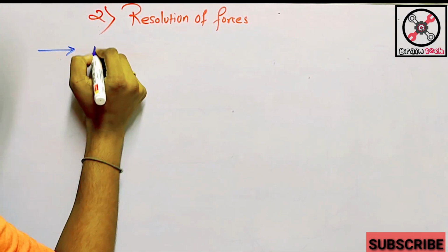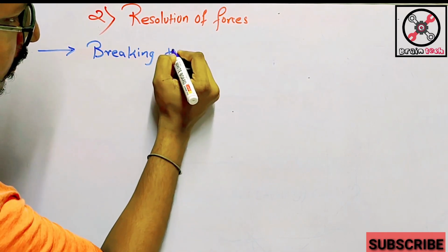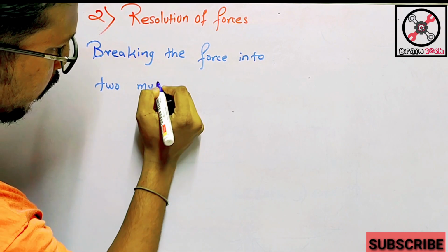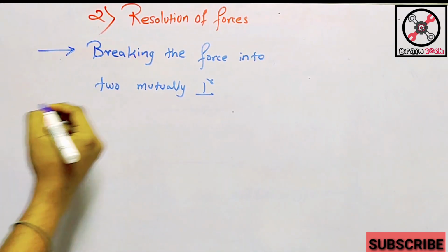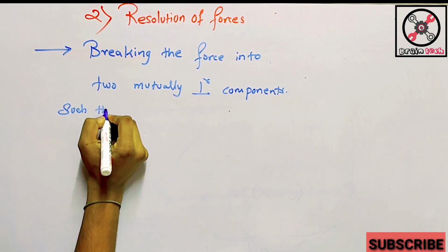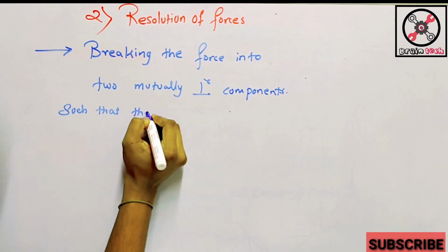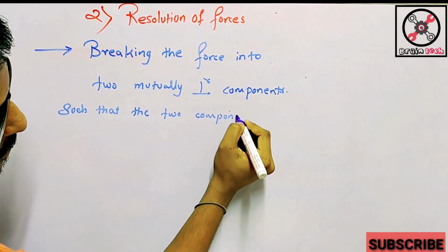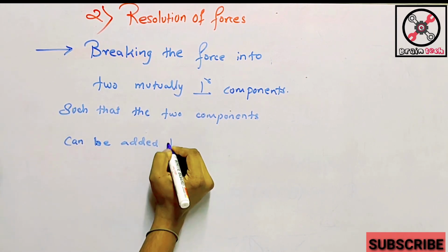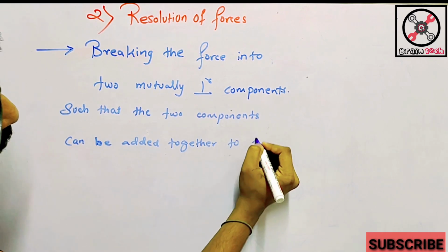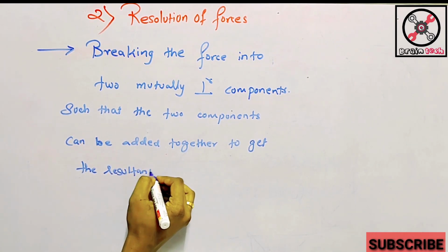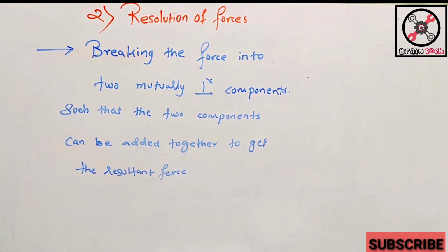Resolution of forces means breaking the force into two mutually perpendicular components such that the two components can be added together to get the resultant force. Now, what does it mean? We'll understand with a simple example.